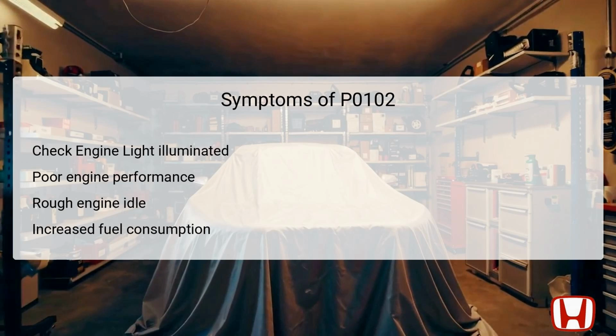This alert indicates that the vehicle's onboard diagnostic system has detected a fault. Additionally, the vehicle may exhibit poor engine performance, characterized by a noticeable lack of power during acceleration or a rough idle when the engine is at rest. Increased fuel consumption could also be a side effect due to an incorrect air-fuel mixture caused by erroneous data from